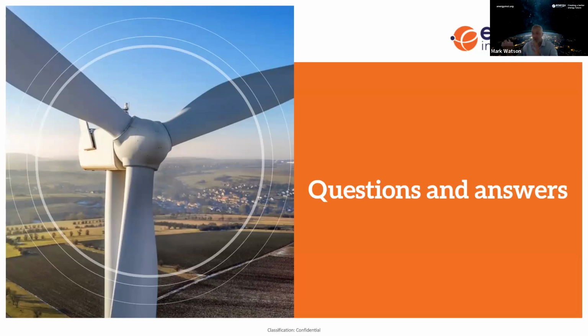So when there's works on both sides of the boundary, this process is for the wind turbine safety rules work on the work side of the boundary. The work on the HV side of the boundary would, in my view, be managed by the HV process. So there could be two separate documents, two separate agreements from the working party. But again, it sounds like that needs planning quite well and understanding what everybody needs to do.